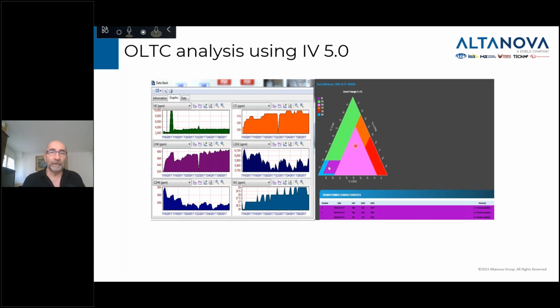It's the same example I showed earlier. So what you can do with that system is really see if there's any deterioration in that OLTC that will tell you that at that point, the customer has to do some kind of maintenance on that OLTC. Again, the response time of the measurement on the OLTC is not as critical as for some other faults I will show. But the accuracy of the measurement is absolutely critical to do the diagnostic using, again, the Duval triangle.